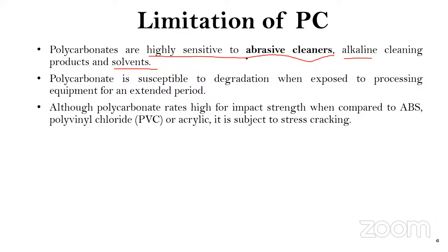They are quite sensitive to abrasive cleaners. If that cleaner is made up of strong alkaline or strong solvent like a chlorine solvent, chloroform or some other chlorine-related solvent, don't use it. That can affect the property of your PC.